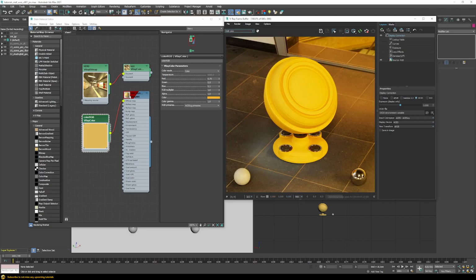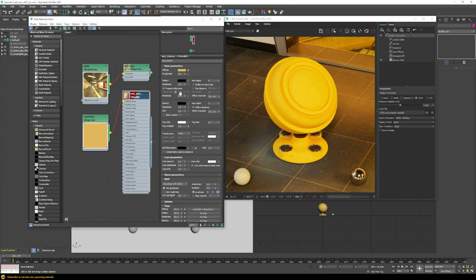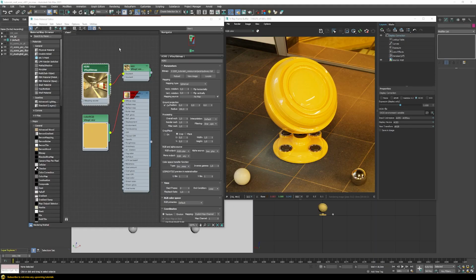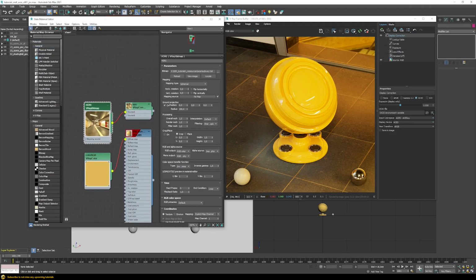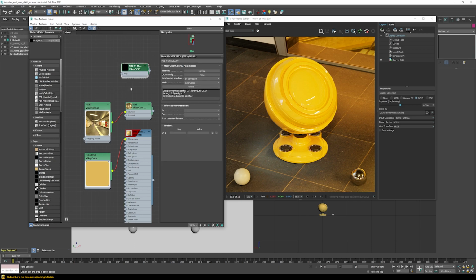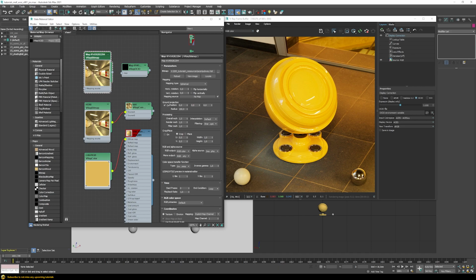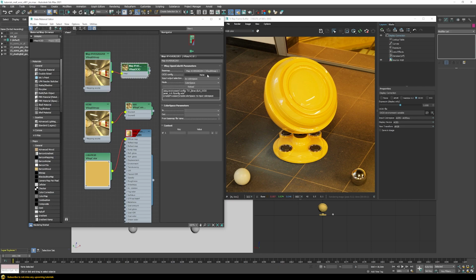Alright, so now let's just add back the reflection color in here again, and then let's take care of our VRayBitmap. So let me first show you how stuff was done traditionally in VRay. There's this node here called VRayOCIO, and if you use this, you can manually convert, for example, bitmaps into the correct color space that you need. So let me just copy this VRayBitmap in here and then map that into in here. And because we set up this environment variable, basically everything is already loaded.